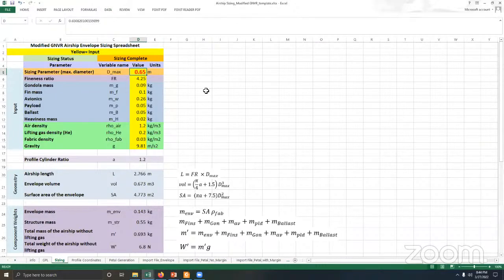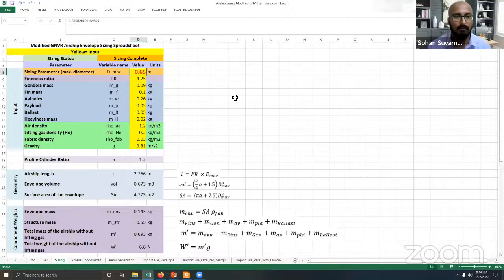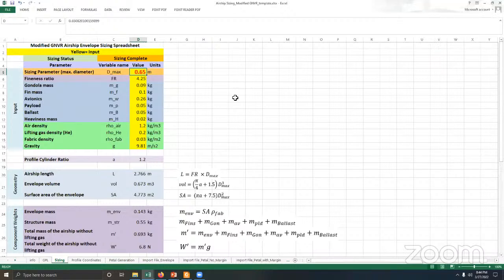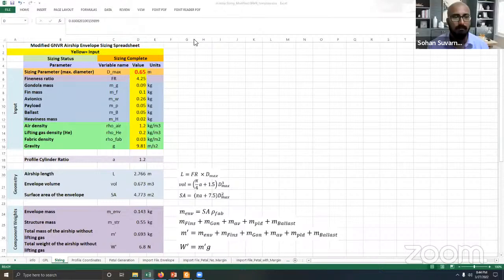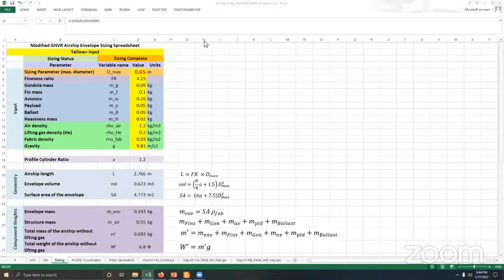The cell that you want to set equal to 0, or to some number, can have an equation, but the cell that is to be varied cannot have anything other than a number. Also, sometimes Goal Seek is not able to get the answer, so it will just keep running in circles, and then you can stop it. If you like the answer it suggests, you can say okay. If not, you can get the original back.